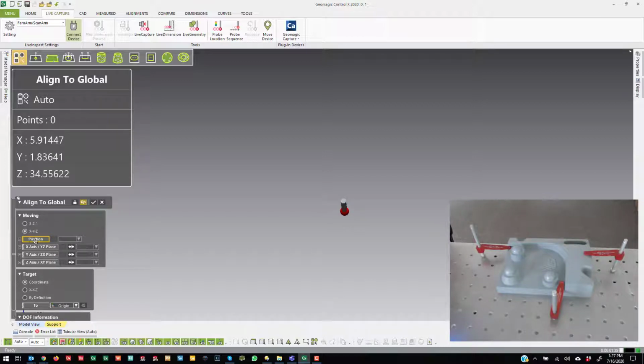What we do is break apart the location of the origin and its directional alignments into separate components here. So there are a plethora of ways of aligning parts, right? And it all depends on how your CAD drawings dictate how you align the part. Today I already showed a 3-2-1 or a plane-line-point alignment.